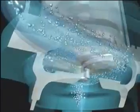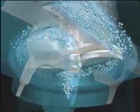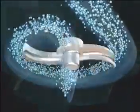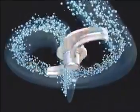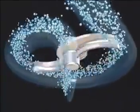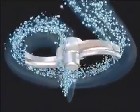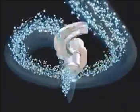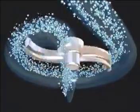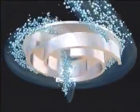Impeller designs generally fall into 4 basic types: open, semi-open, enclosed, and vortex. The open impeller design has no backplate, and the vanes extend from the center of the impeller outward. Pumps incorporating an open impeller design are used chiefly in low to medium pressure, high capacity pumps capable of handling screened or unscreened solids. A semi-open impeller has a solid backplate to which the vanes are attached.